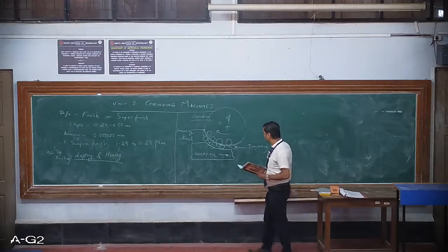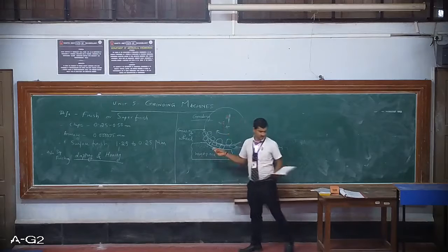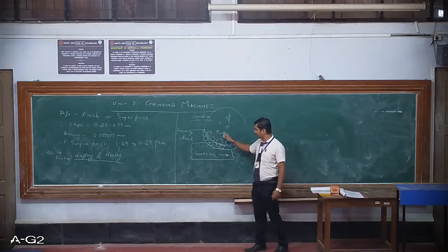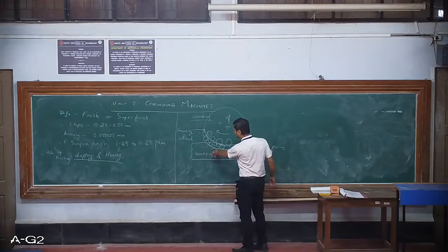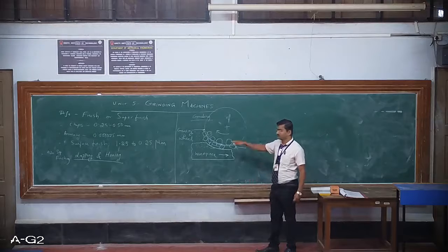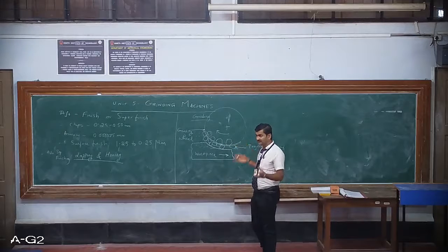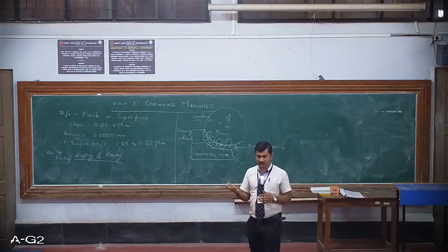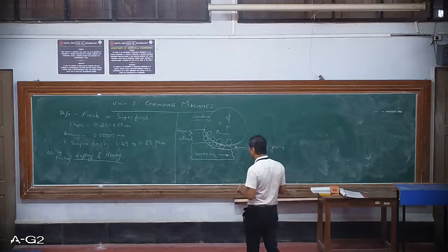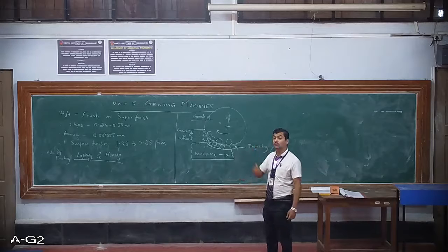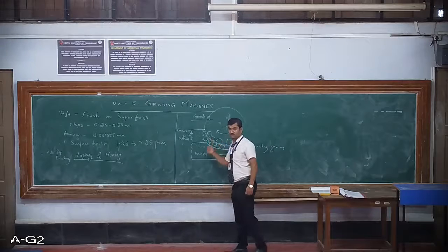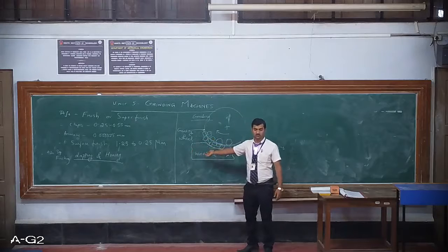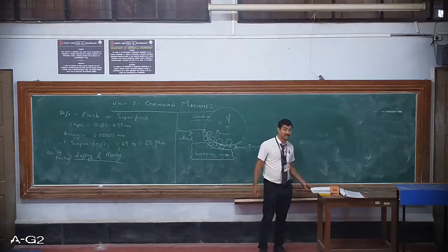The concept of grinding implies that when you bring this abrasive wheel in contact with the workpiece, its surface gets abraded by the particles. There is an interaction between the abrasive and the workpiece in such a manner that fine particles are thrown away from the surface, and powdered form of chips are collected or thrown at the other end. This is the concept of the grinding wheel.